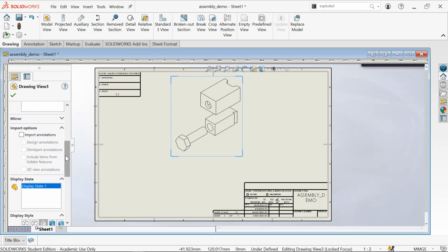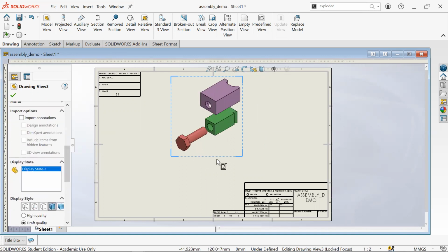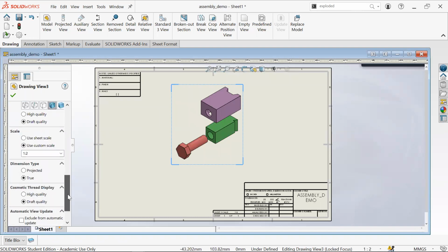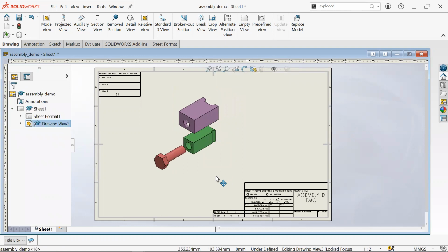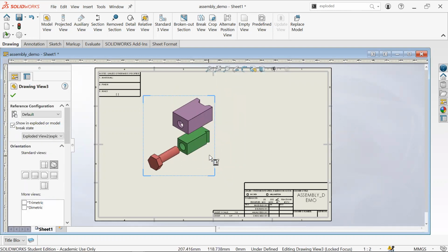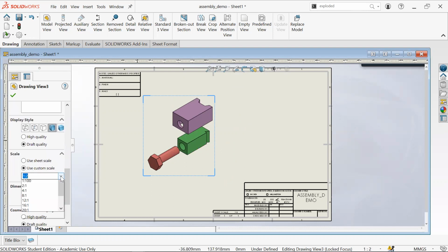For the exploded view, it's fine if you just leave it in colors with lines. That way it looks nicer. And a common issue is not filling up the page. Make sure your part or your assembly fills up the page. You don't want to have a humongous page and have like 4 little views. That's a poor use of space and makes it harder for not only grading, but for your audience to interpret your drawing. So make sure they're displayed in a decent ratio, in decent scale.